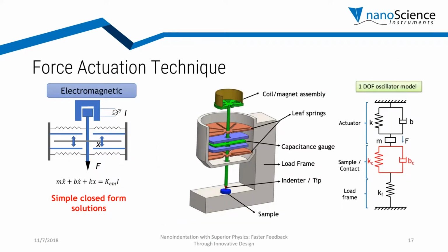Now, we mentioned earlier that we have this nanoindenter tip and it is applying load. So the natural question is, how is this load being applied? The answer is that the tip is attached to something called an actuator, or commonly referred to as the indentation head. Those indentation heads could be based on different principles. In our case, we are using the electromagnetic principle.